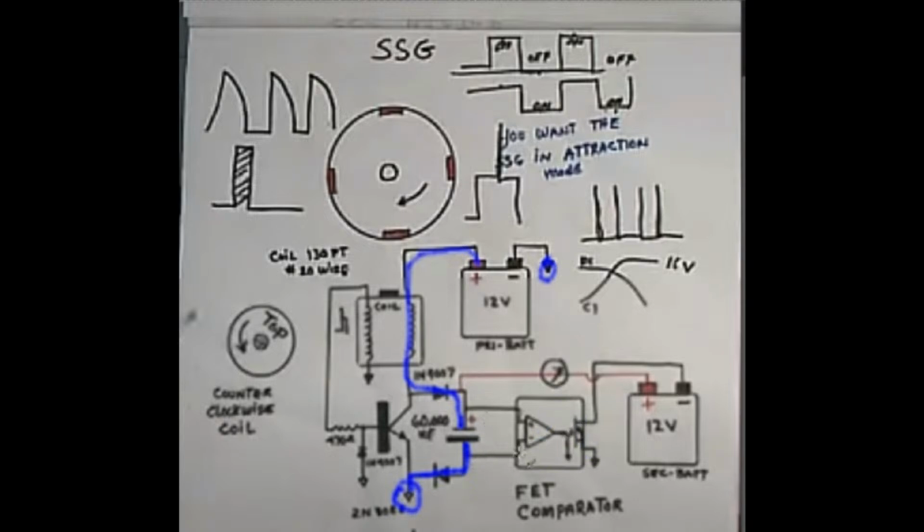Sorry, yeah, this must be a different drawing, but he puts a Zener, 18 volt Zener, to protect the logic gate, I guess, which does the regulation of the voltage back to the charge battery. So why did he have that 18 volt Zener? To protect the logic gate from the flyback. So only 18 volts of the flyback will get to the gate, or to the logic, or 18 volts or less. That's what I'm guessing he has the Zener for.